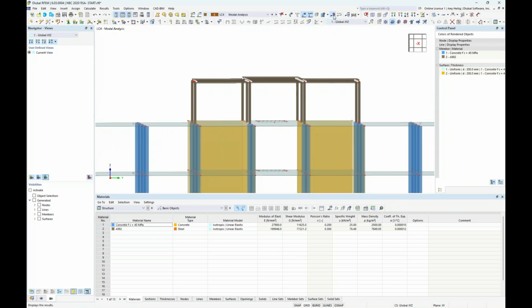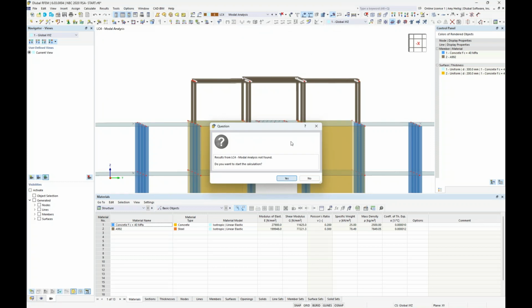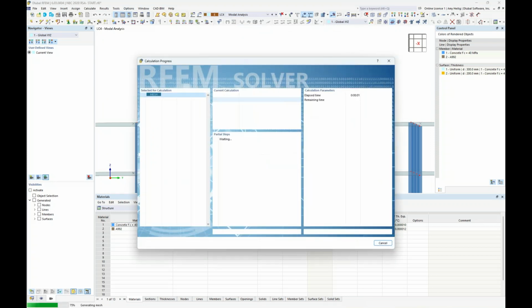We're going to rerun this calculation, and remember now that we are completely neglecting the masses from the steel members, but rather we have now inserted that single point mass load at the top of the concrete structure to simply redistribute the mass. And our hope is by still solving for 10 different eigenvalues that we see slightly better